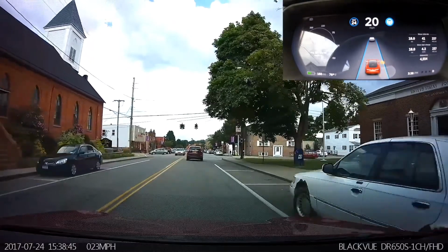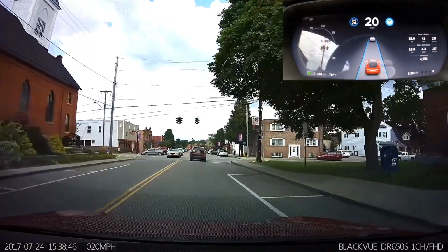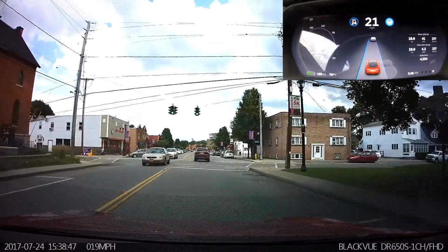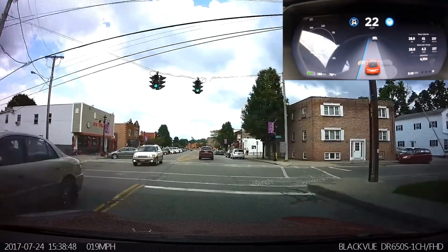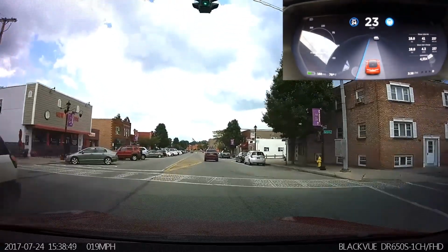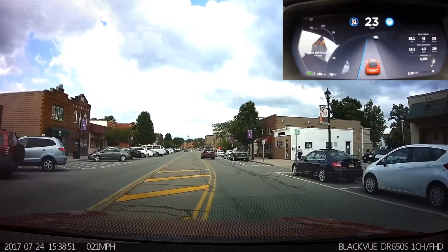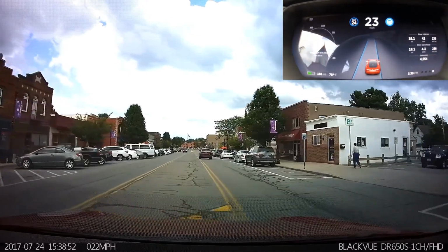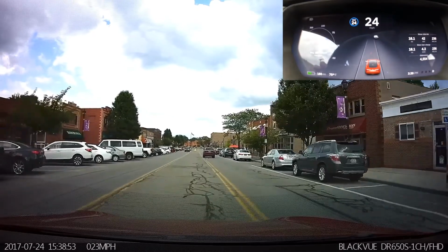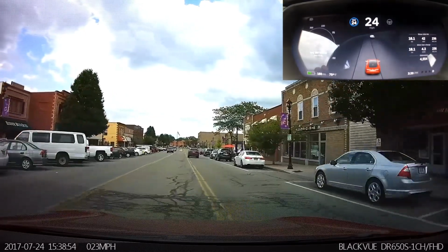The video here is going at half speed through a town. You see going at a very slow speed, going through an intersection where we lose the lane markers. It has the left one only, goes through the intersection, loses the right one, picks up the double yellow line on the left, misses the one on the right. Now thinks the one on the right double yellow line is the middle of the lane. I'm stuck in the middle of the road now. Obviously a big failure.